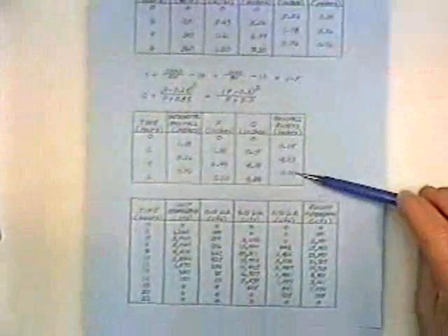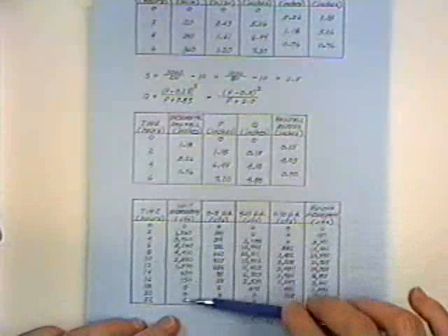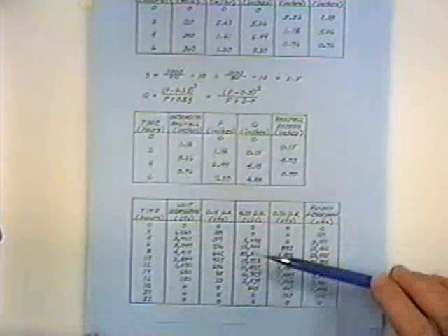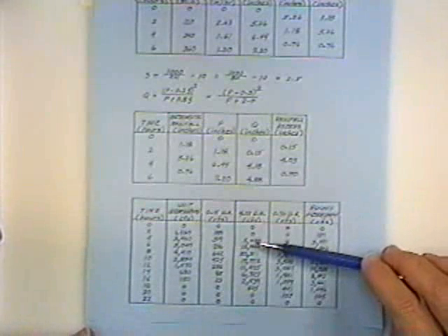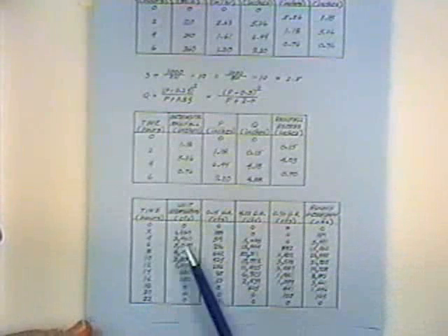Third 2-hour increment of rain, we've got that direct runoff volume. Each time, we take the unit hydrograph that we computed in the previous example, we ratio ordinates in proportion to the direct runoff volume, and then each 2-hour increment of rain began 2 hours later, so we lag everything by 2 hours, and then we add them across to get the runoff volume.